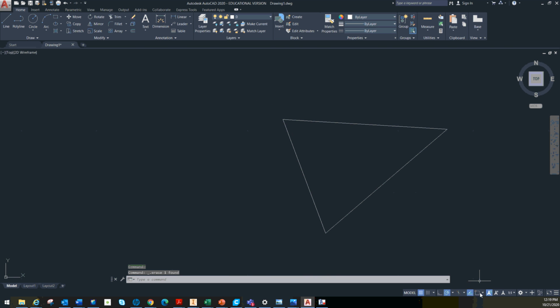You can also customize what your object snaps to by selecting these things. Make sure you have things like endpoint and center and intersection turned on. Those are important ones that you'll use a lot. Okay. Next thing we're going to look at is our offset tool. Our offset tool is wonderful. What it'll do is it'll allow us to, say, take a straight line of a certain length and draw a replica of it an exact distance away.